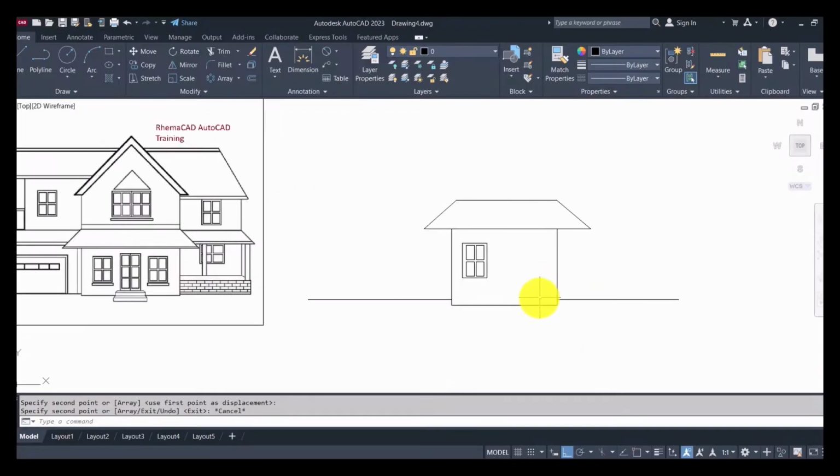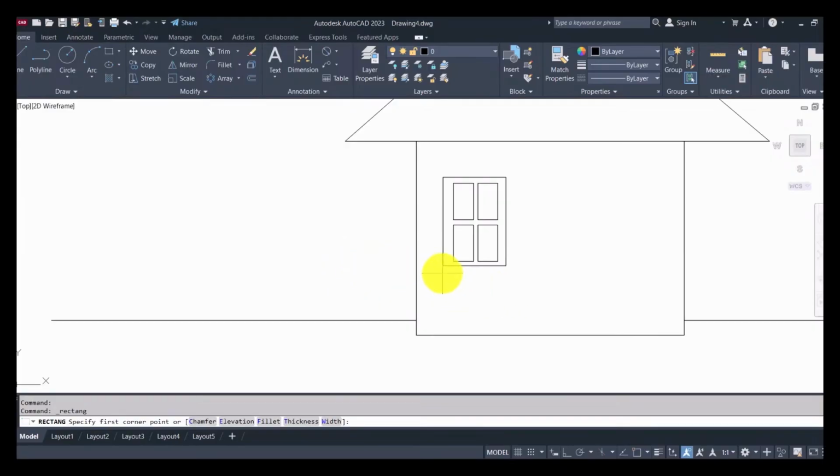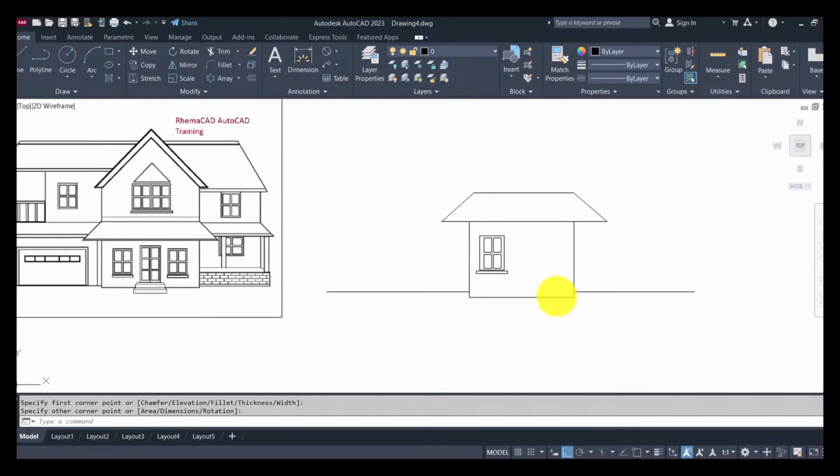Okay, all right, this is good. Then I'll draw a rectangle below it. Okay, so this looks good for me. So now you can see I have two copies of the window here. So I'll make a copy of this window, enter, then select base points. Now my auto is active, which will enable me to copy on a straight line. Okay, all right, I've been able to do that.